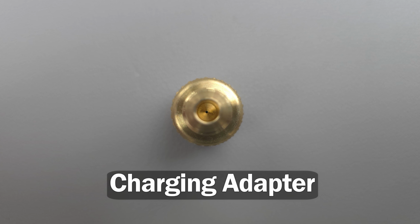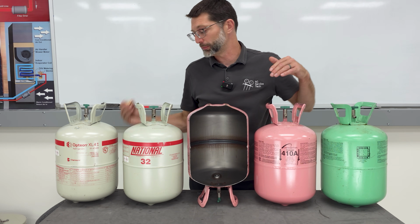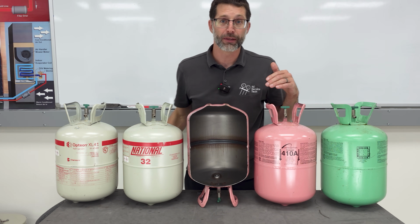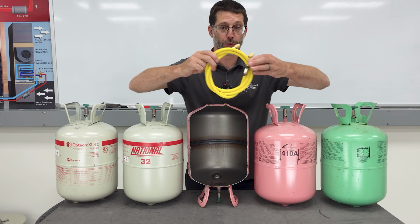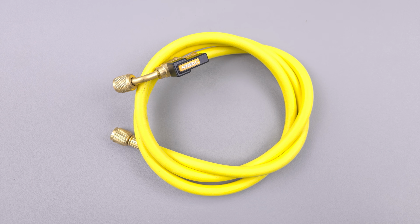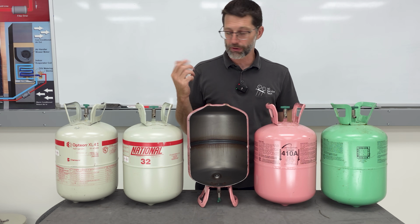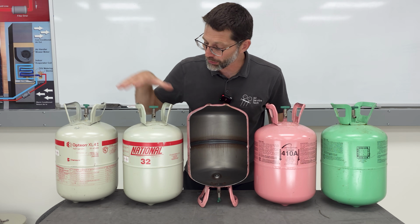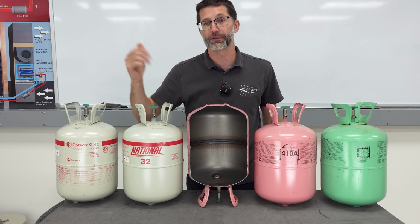And so it takes the liquid out of the bottom of the tank and flashes it into a saturated mix of both liquid and vapor. And so by the time it gets over to the system, maybe through your refrigerant hose, it's going to be mainly in the vapor state. But if you're charging refrigerant into a running system, when you're adding, say, R-32 or R-22, you can just charge it as a vapor, just a little at a time, and that's fine.